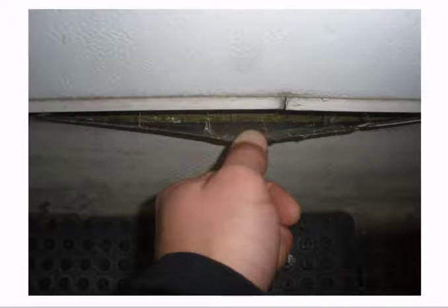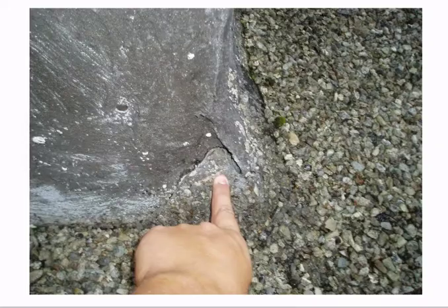Well, a typical contractor may just push that flashing back up and caulk off the top of it. Again, short-term fix. But the best repair you can do on that is pull that flashing down, expose that back edge of that flashing, put some water cut-off sealant in there, fasten a term bar on there every 12 inches, caulk off the top of that term bar. And then you can go above and beyond that by putting on a counter flashing over that, kind of the belt and suspenders approach. Good.